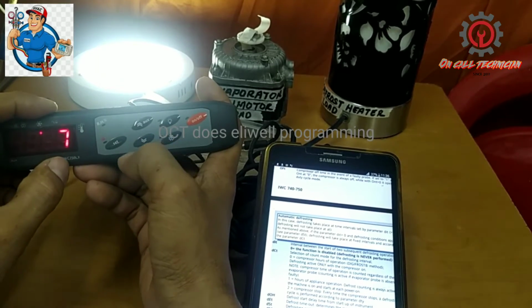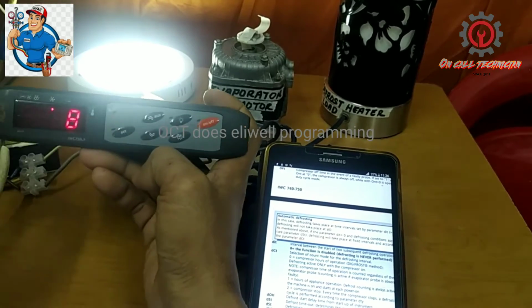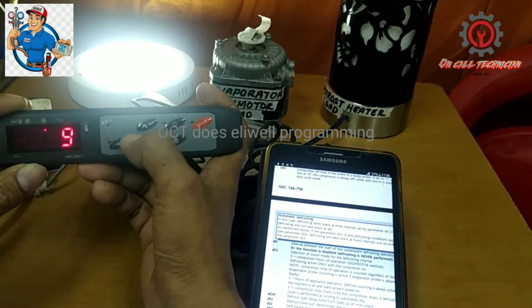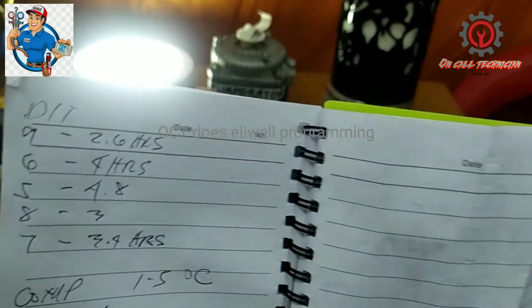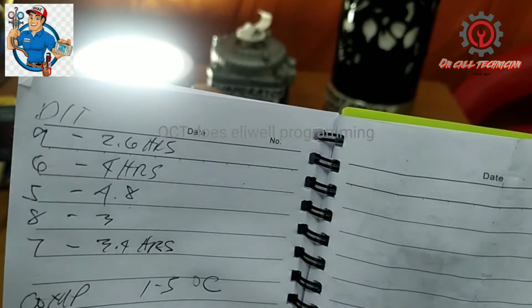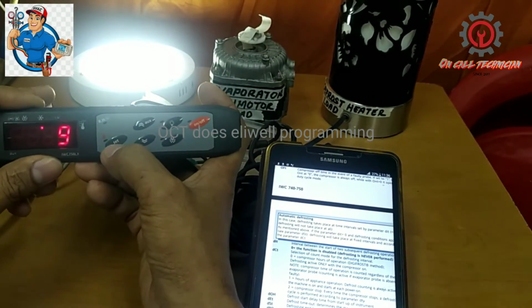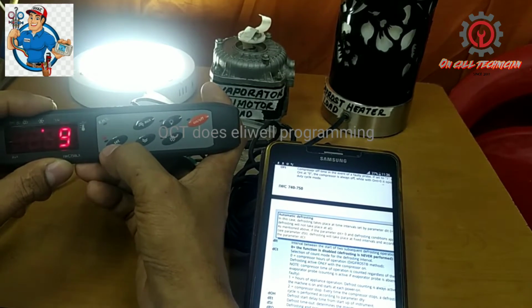If you want to use 15 minutes, just add this. Okay, add it to 8. Okay, here 9. 24 divided by 9 is 2.6. So every 2.6 hours, the defrost heater or hot gas will engage, and the compressor by that time will stop.